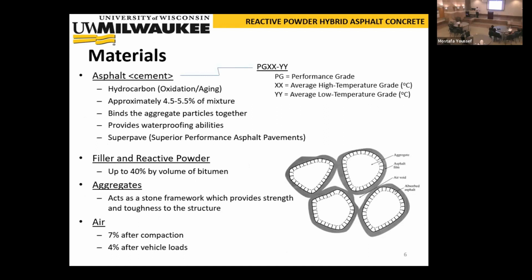In doing so, we had to select our materials carefully. We wanted to use an asphalt that is representative of the market, and also modify it with different modifications so it more fully encompasses the entire market. We wanted to get to a volume concentration that is really economically feasible and mechanically beneficial if we get there. And as we build our concrete mixes, we build them to a certain compaction level, so we have to maintain a certain level of air voids within the mixes.